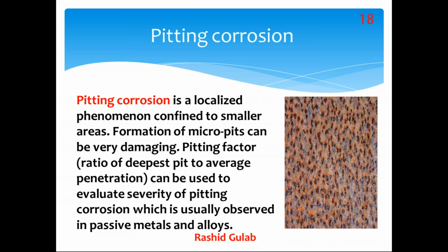Most of the time in our daily experience during blasting, the people who are involved in the painting and coating field know it well: after blasting, when we are checking the surface profile, if we find any pitting, in some cases we are also rejecting the material. We are not going to paint that material, because this pitting is very critical and very dangerous for the next process. During pressurization, during the water hydro test, or any kind of pressure testing, any problem can happen. So due to this, we are going for NDT for this process.